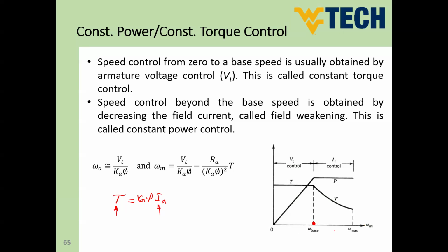So increasing the speed, and if the torque is going to be constant, this means the power is going to increase. So you cannot increase the power over the rated value of the machine. So the idea is, if you would like to increase the speed, this is possible. However, you have to keep your machine power constant. Constant at what value? At the rated value of the machine.